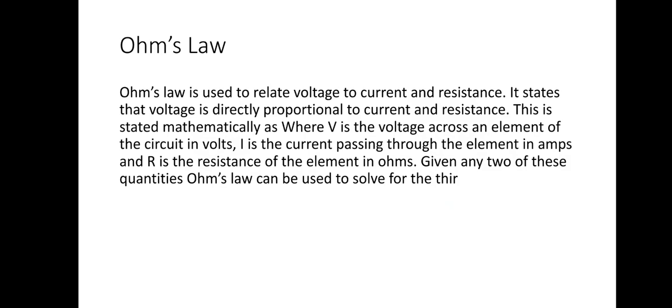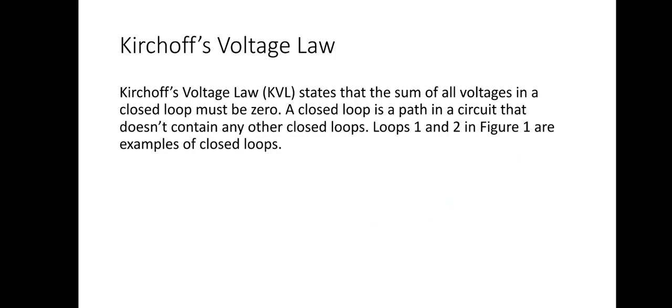KCL example: minus 10 ampere and minus 5 ampere are coming into the center, and minus 15 ampere is leaving the circuit, which shows minus 10 plus minus 5 is equal to minus 15. So leaving is also minus 15, which satisfies the equation current entering node is equal to current leaving node. Now we'll talk about generalization of KCL.